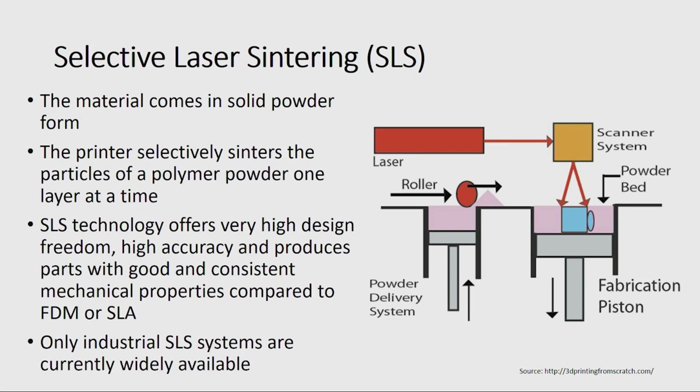A definite quantity of powder is transferred from the reservoir to the build volume, and the thickness of the powder delivered to the build volume is controlled, and the roller will move from left to right, and again come back to the initial position, such that the uniformity of the layer delivered to the build volume is consistent.